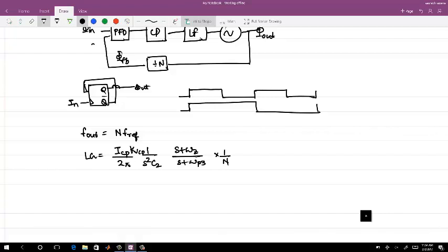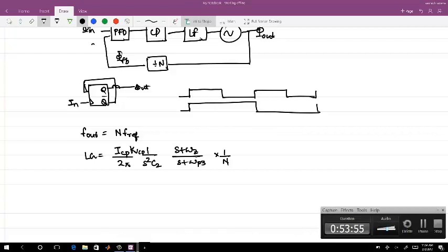So you have to accommodate this n factor only in the loop gain, nowhere else, because everything else is in terms of phase, or because we did most of the analysis on the phase margin with respect to unity gain frequency. So you can do the whole analysis and it will be a clock multiplier. Okay, let's stop here. Any questions so far?